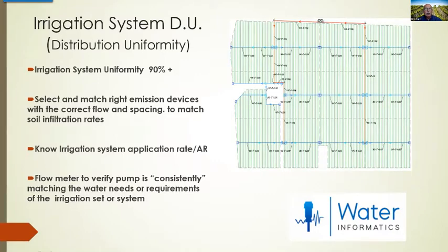One of the things that you can do is that the NRCS has programs that you can actually get your system tested. Now that people use pressure compensated emitters, the uniformity's gone up, but that can be coupled with some problems in a pressure compensated system if the flows of your pump are decreased, or you run them at low pressures.